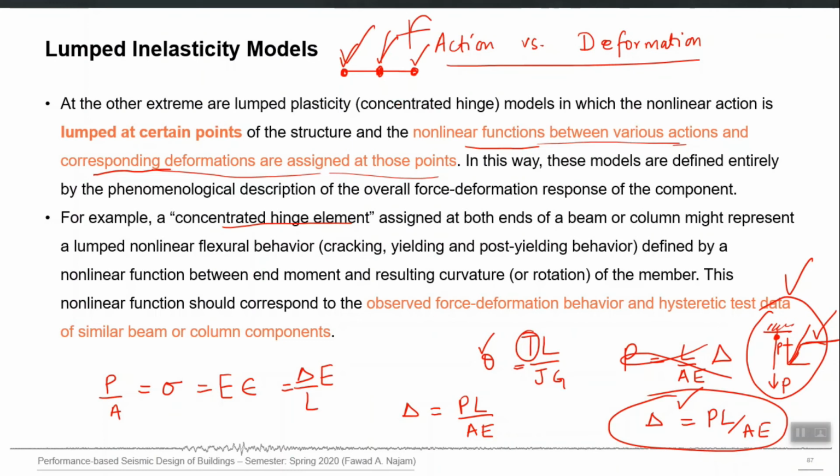The program will monitor the demand shear force at that point, and if it increases beyond the yield shear capacity which I give in the form of that curve, the program should be able to tell after the analysis that this beam has failed in shear.